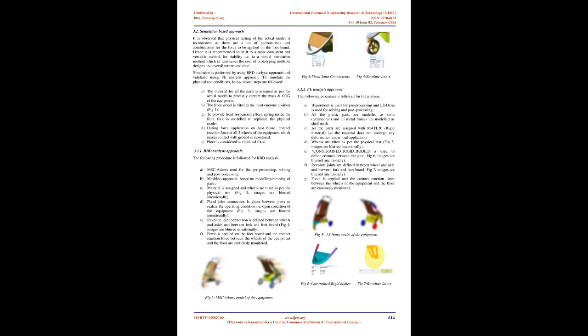Simulation is performed by using the RBD analysis approach and validated using the FE analysis approach. To simulate the physical test conditions, the steps shown below are followed. The material for all the parts is assigned as per the actual model to precisely capture the mass and COG